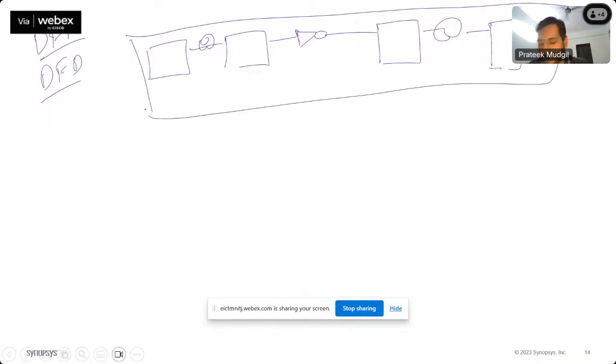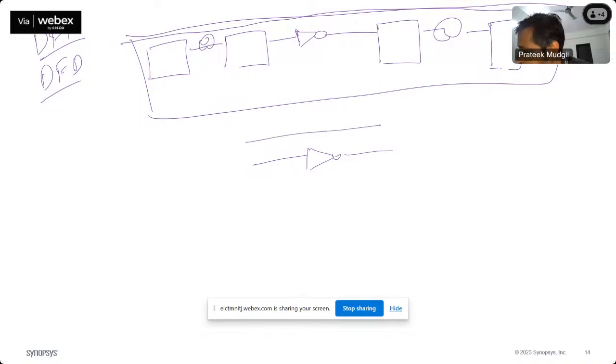And when I am fabricating it, we see the VDD rails and metal layers and everything running around, right? So what happened, right? This is my logical layer, the logical layer of the data path, and this is a VDD path, right? And because they were very near, there is a bulging out of the VDD layer at fabrication time, right? And we see that there are two cases, that this line is very near to it.